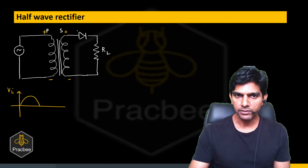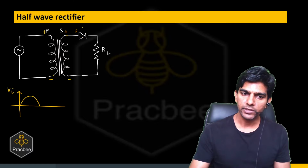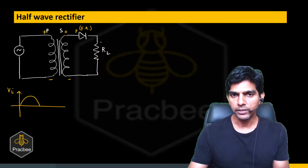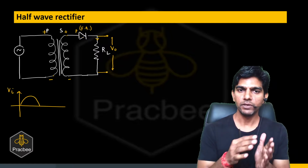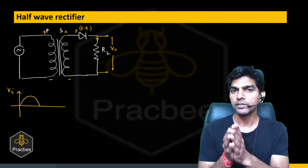Then the P side of the diode is connected with the high potential. So this diode is forward biased, right? If the diode is forward biased, then it will be conducting. So there will be some current through this load, and we will measure this potential difference. This is the output voltage. So you can see we'll have a reading when the diode is forward biased.